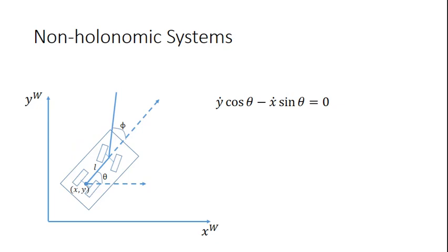So that's where this stuff comes into play. Let's look at a car-like robot. Car-like robots are also subject to this constraint, but they're also subject to a second constraint. The one that you're looking at right now, the normal non-holonomic constraint, is about the reference point, so the back wheels. The back wheels of the car are always moving with this equation, but we also have one for the front wheels of the car.